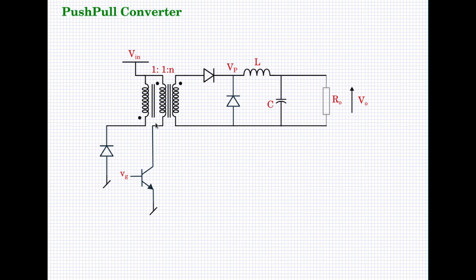During the time when this primary winding is off, instead of putting the energy into the supply, let us put the energy into the output. So that is the concept which will come in the push-pull. So instead of calling this a demagnetizing winding, we will call it another alternate primary which will put energy into the output instead of into the input.